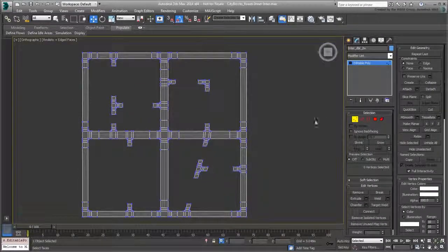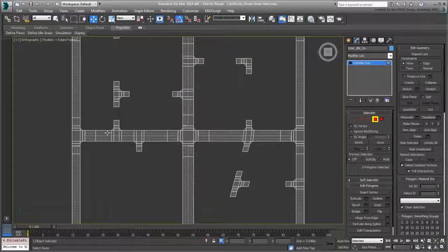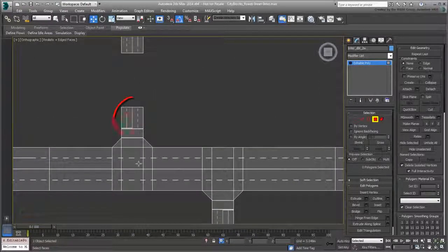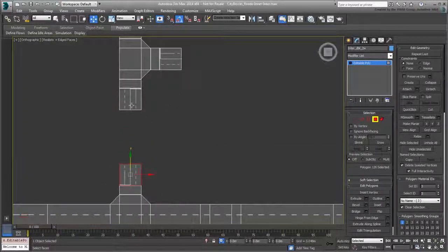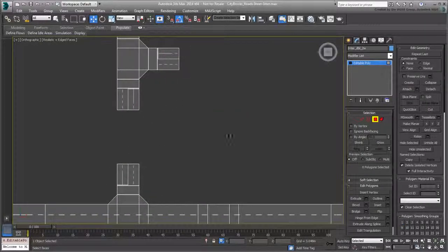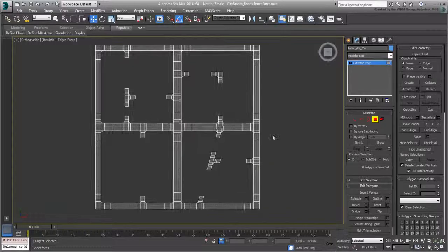Next, you need to adjust the materials for the stop line sections. They are still showing 4 lanes, as this was copied over from the main roads. Depending upon whether an inner road is a one-way or a two-way street, the markings for the stop lines, and the road for that matter, will be different. For that reason, you need to account for both situations. As an example, let's assume that most inner roads will be two-way streets, except for that little stretch here that will only flow left to right.